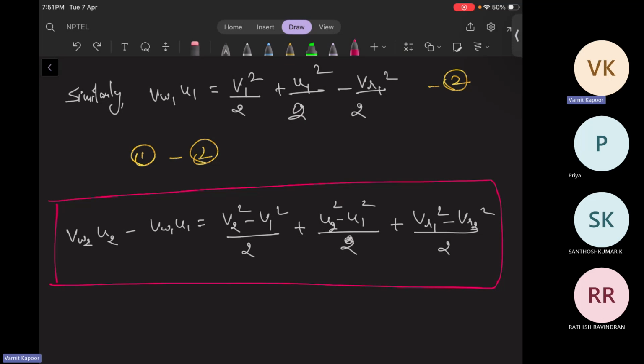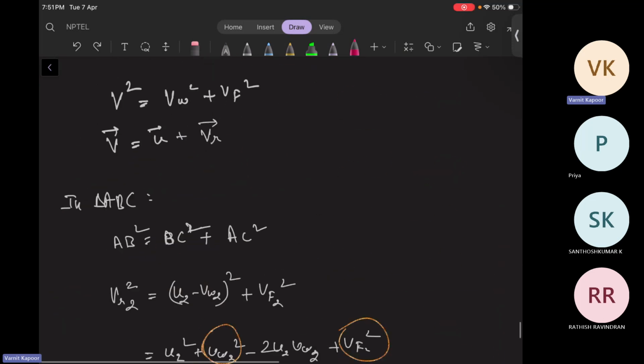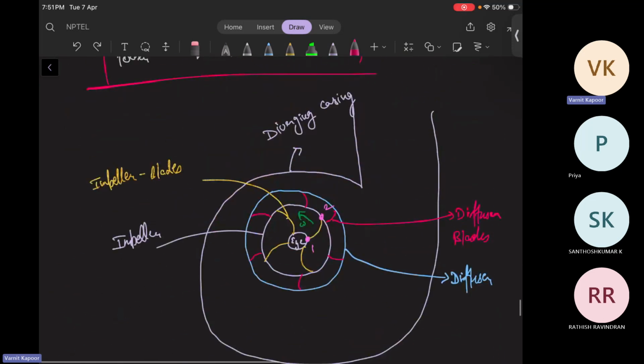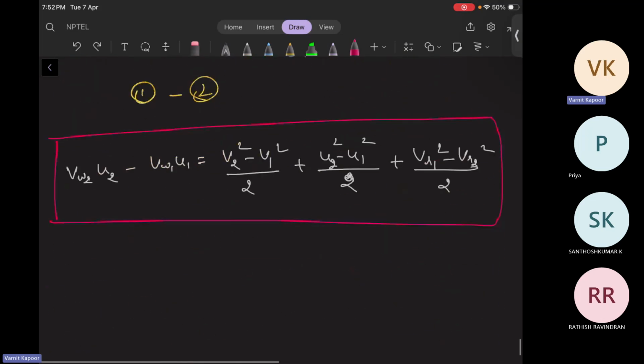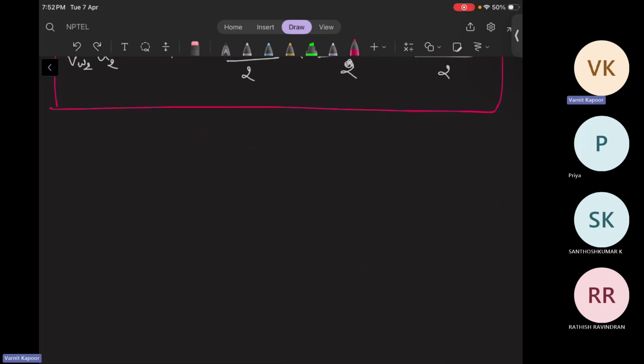Then that fluid from section 2 will go into the diffuser. Initially, you increase the kinetic energy by creating a vacuum at a higher speed of rotation of the impeller. The fluid discharges through the impeller to section 2 and enters the diffuser, where the pressure increases by converting that increase in kinetic energy to pressure rise.